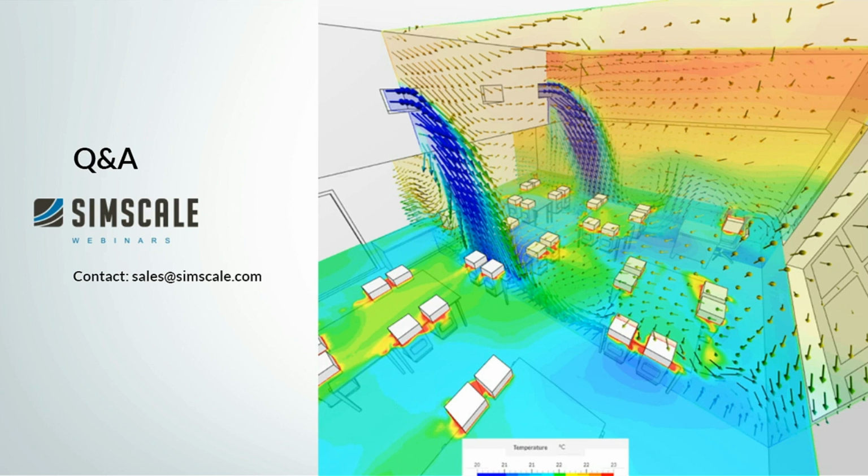So we want to have a large-scale analysis on the building and its surroundings. That's where we use the incompressible LBM solver. The incompressible solver itself is used more on internal flow cases and is based on a derivation of the OpenFOAM solver.